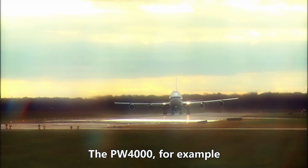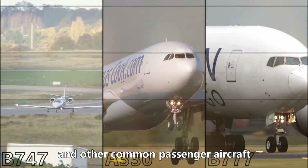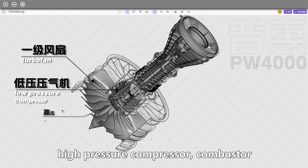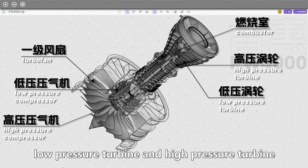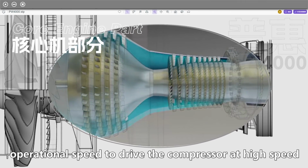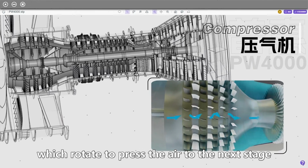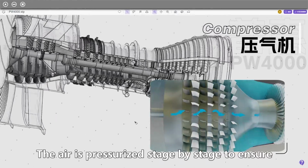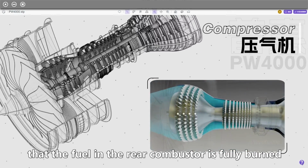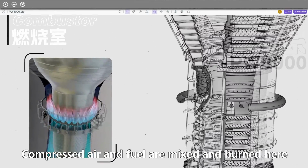The PW4000, for example, is a high-bypass engine that is commonly used to drive the Boeing 777 and other common passenger aircraft. It consists of a turbofan, low-pressure compressor, high-pressure compressor, combustor, low-pressure turbine, and high-pressure turbine. At startup, the engine rotor is accelerated to a certain speed to drive the compressor at high speed. The compressor is a set of discs with blades, which rotates to press the air to the next stage. The air is pressurized stage by stage to ensure that the fuel in the rear combustor is fully burned. The combustor is a ring-shaped tube with an igniter plug. Compressed air and fuel are mixed and burned here.